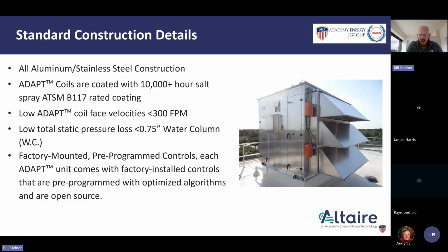They define the cross section of that unit. Because I'm only doing 20-30% outside air, I could have a bigger coil that still fits within that footprint and run it a lot slower. Additionally, that helps me with performance, right? The slower we run a coil, the better performance we're going to see across it.